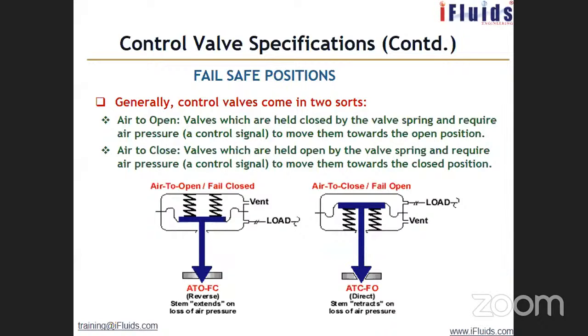So it all depends upon the pressure drop across the valve. Will pressure drop affect the selection of valves? Definitely. If you want less pressure drop, you have to take that kind of valve which is not dropping much pressure. But if you are more interested in regulation than pressure drop, then globe valve is the best. In most conditions, the globe valve is preferred for regulation. It has an impact on the type of valve.